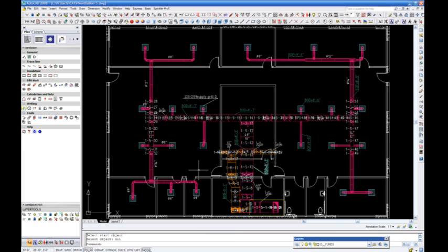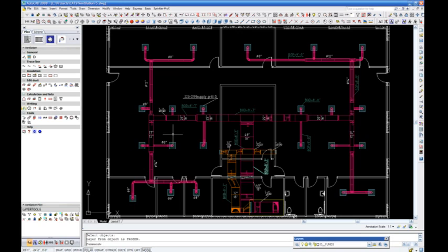We will repeat this on the supply air system. The software finds 60 pieces. We will select S for supply, our start point, and assign. Now the item numbers can be relocated to a position where they are better readable on the drawing.